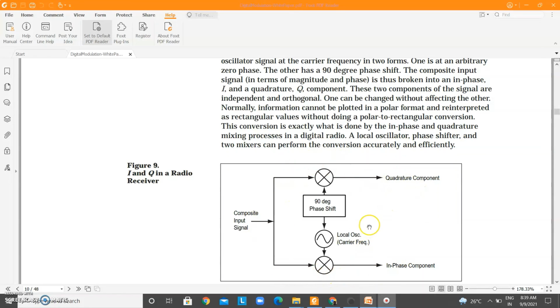This also is coming from the IQ format. Because we are using the IQ format, at the receiver we have a unit like this. I hope it is clear how you draw this. And these two blocks are used fundamentally in all the transmitters and receivers of digital modulation schemes. So next we will see how it is being used, or how you can draw the transmitter side and the receiver side for each of the digital modulation schemes.